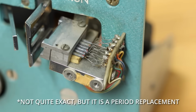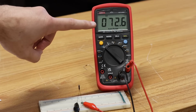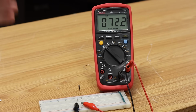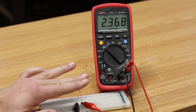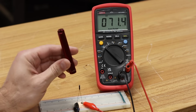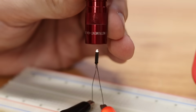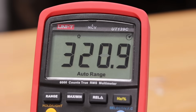So if we perform that same test on this 3F42 photodiode, you can see that it's currently sitting at about 70 kiloohms, and that's because the photodiode is facing straight up, and that's where the lights in the room are. If I cover this up, you can see we bump up to like 1.5, 2, 3, 5, 7 megaohms. And conversely, if I shine a flashlight onto it, we're down into like 100 ohms. Less than 100 ohms. That's insane. Look at the range that this thing has.